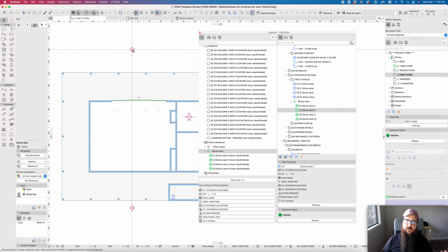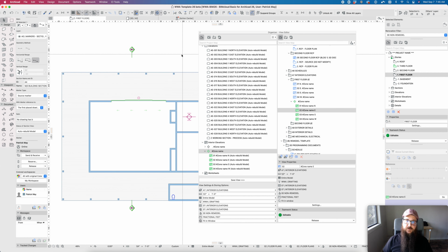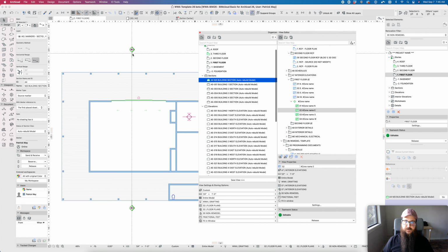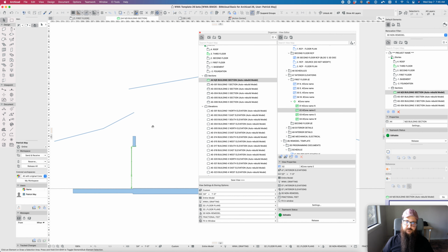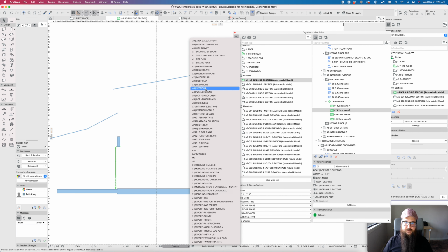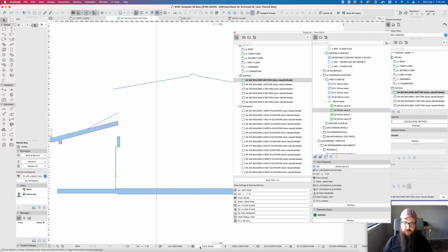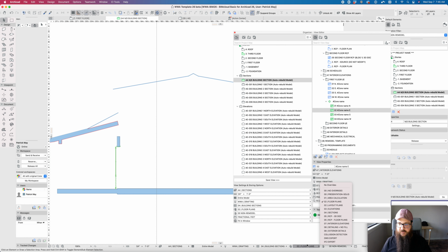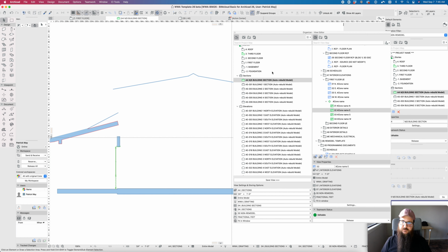There are other ways to create views from a viewpoint. So here's this section marker that I created before. I've renamed it North-South Building Section. If I right-click and open the current settings of that, wait for that to open, here's my building section. What I can do is down here at the bottom, set this to my sections layer combo, partial structure display, entire model, pen set is drafting, the model view options is going to be building sections, the graphic override, again, going to be building sections or sections. The renovation is non-remodel, and feet and inches or fractional feet.